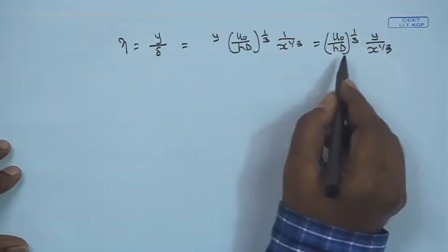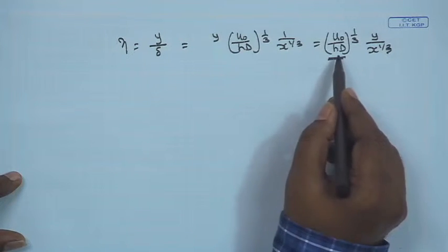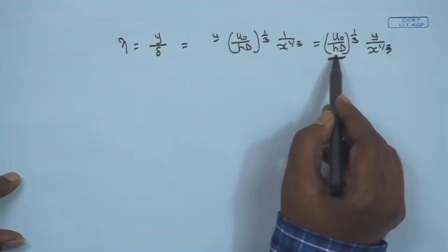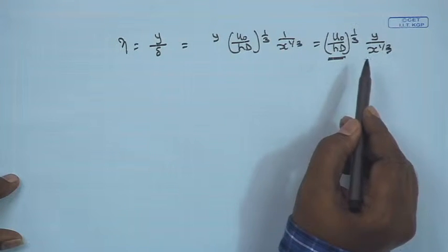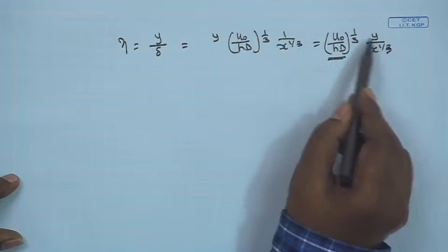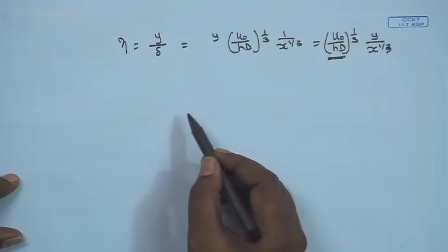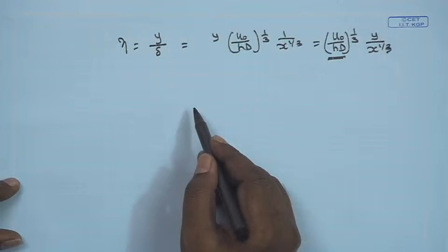Why we have put this term is because u naught is a constant, h is the geometry half height of the channel, d is the solute diffusivity which will be assumed to be constant. So, with the combination of all these parameters, you can see that eta will be a dimensionless number. So, eta, the similarity parameter, does not have a dimension.